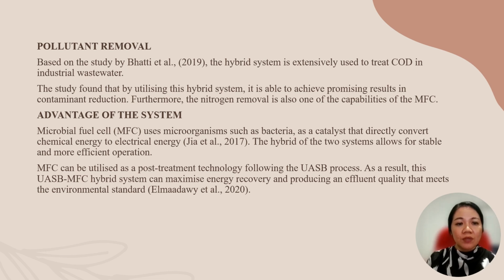For the advantages of the system, microbial fuel cell MFC uses microorganisms such as bacteria as a catalyst that directly convert chemical energy to electrical energy. The hybrid of the two systems allows for stable and more efficient operation. MFC can be utilized as a post-treatment technology following the UASB process. As a result, this UASB MFC hybrid system can maximize energy recovery and produce an effluent quality that meets the environmental standard.